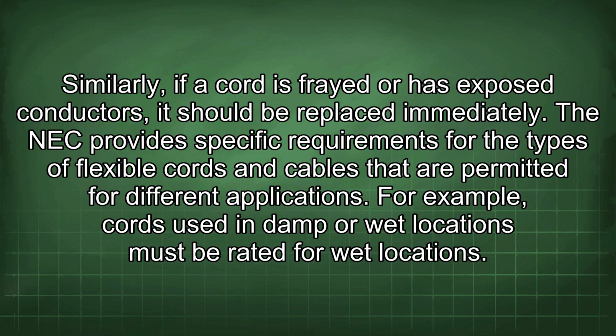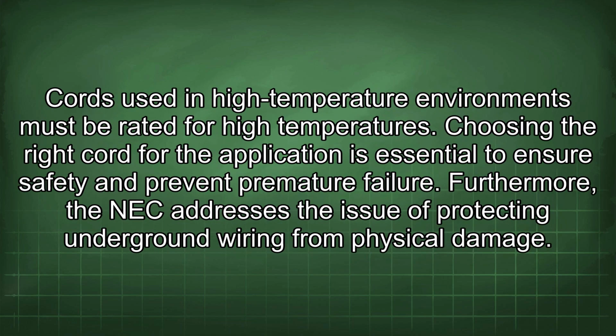The NEC provides specific requirements for the types of flexible cords and cables that are permitted for different applications. For example, cords used in damp or wet locations must be rated for wet locations. Cords used in high-temperature environments must be rated for high temperatures. Choosing the right cord for the application is essential to ensure safety and prevent premature failure.